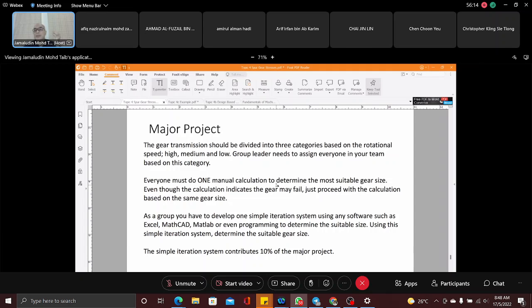Right, that will be the minimum power required. Okay, and you check the output because you have two. You can have one input or two outputs, depending. If you have one motor, then you can design one straight to the end. For example, let's say you take one motor and you have to reduce to a certain RPM. For example, the input you choose is a 1,300 RPM motor. At the end of the day, you have to reduce to 300 RPM. What you should do is that reduction, and that will be your gearbox.